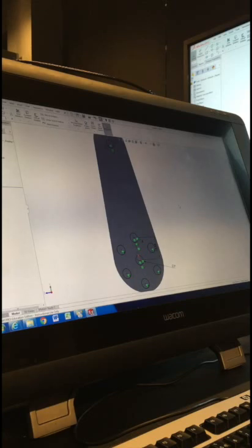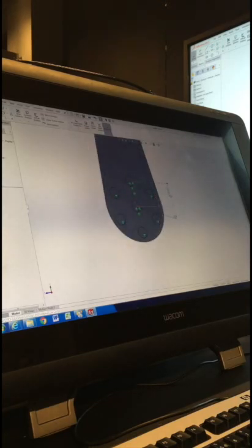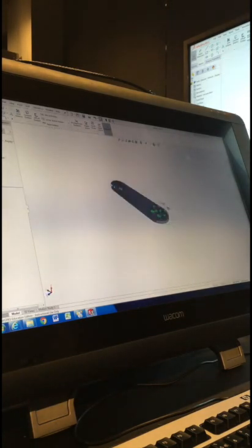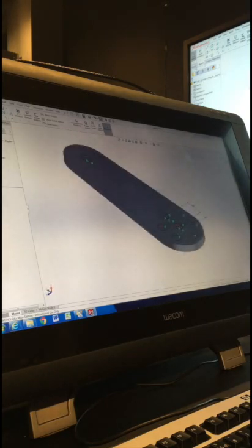And that means that later on, when our client tells us, no, those holes are actually 11 millimeters, you just change that dimension there, and that will update all of them at once, rather than having to update multiple holes. The dimension here that was created by the pattern, just make that 15. And then we can see our sketch is ready now.